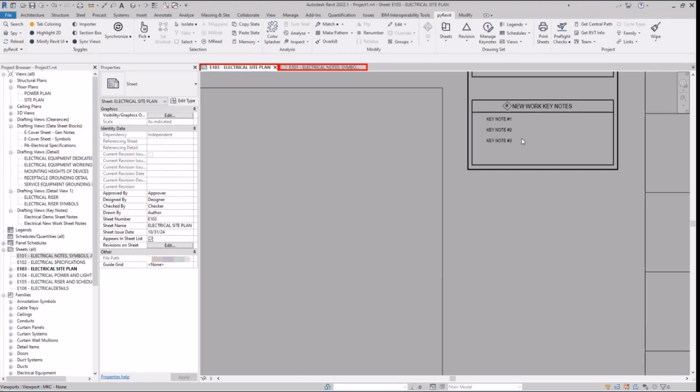And then also this, I don't know if I learned this from you or from someone else, is be careful of the verbiage you use when you say electrical contractor to provide or electrical contractor shall furnish. All of those things mean different things, and they don't necessarily mean that they're actually installing it. I did learn that the wording you use matters in telling them what they're doing, because providing doesn't necessarily mean that they're installing it. That's correct, right?